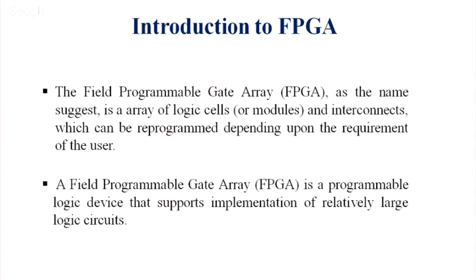There is no type of program storage. There is a direct linkage of your fuses with your logic gates, so there are no sequential circuits. There is massive parallelism in an FPGA, which means you can implement parallel algorithms. In a single FPGA, you can create a number of controllers that are interconnected but work independently. In the case of a microcontroller, we have to combine them with the help of an interrupt handler or some other techniques.